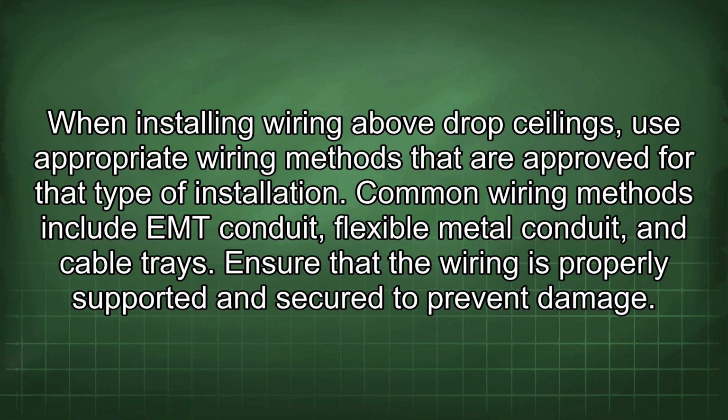When installing wiring above drop ceilings, use appropriate wiring methods that are approved for that type of installation. Common wiring methods include EMT conduit, flexible metal conduit, and cable trays. Ensure that the wiring is properly supported and secured to prevent damage.